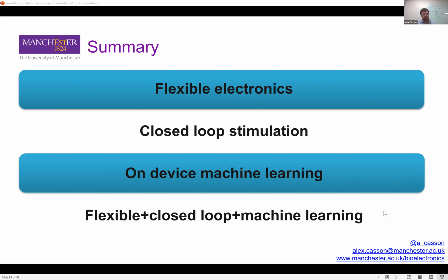And when it comes to the generation of artifacts, what tends to matter isn't so much the absolute impedance number, but the balance of impedances across the head. So when we say typically we want a contact impedance of less than 10 kiloohms, that's not strictly true. What we want is all the electrodes to be matched to within 10 kiloohms. The easiest way of doing that is to have all of them, as an absolute number, be less than 10 kiloohms. We don't have the kit to do this.